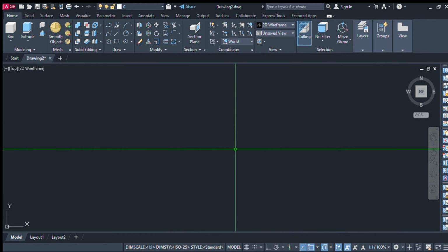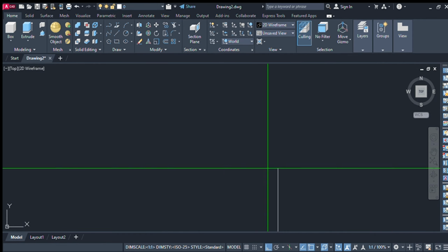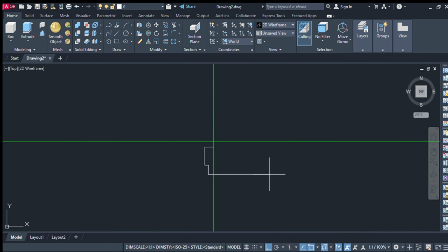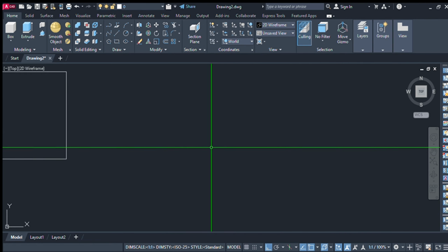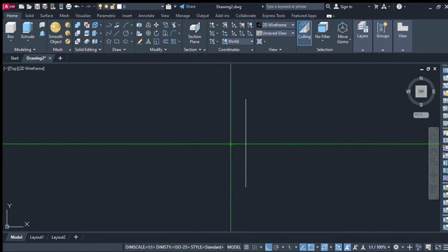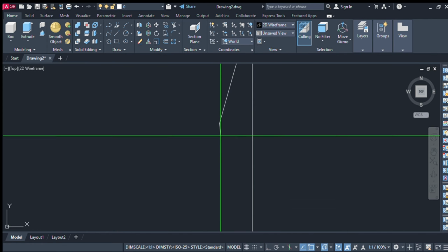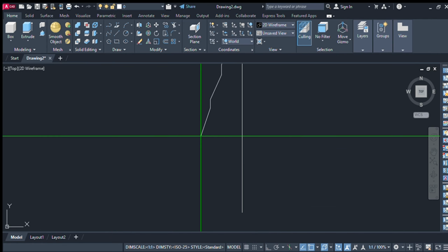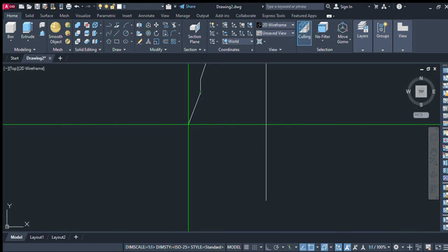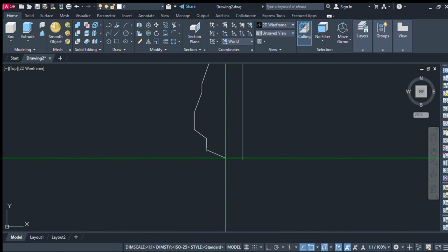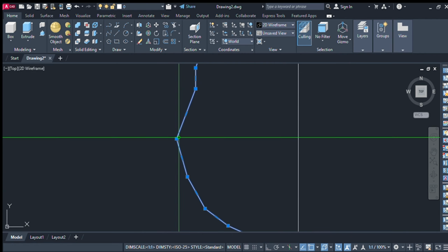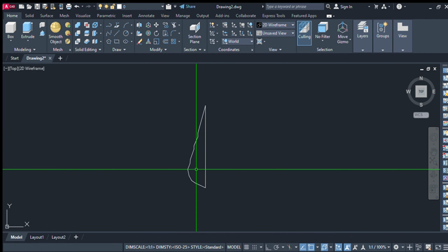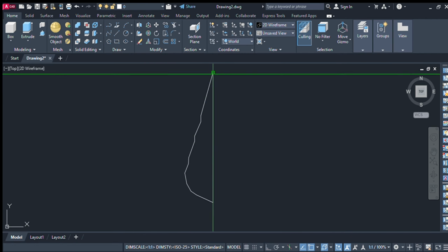After that, I make the base of the chandelier and the dimension is based on my preferred size, and I use the command polyline to apply the revolve command. After I made the base, I create the water drop effect of the chandelier and I use the command polyline, and I use the mesh to the object to achieve the crystal effect of the chandelier. After that, I modify the shape to smoothen it and I revolve the object using the revolve command.